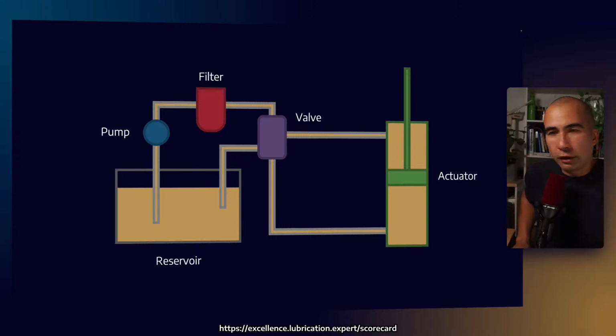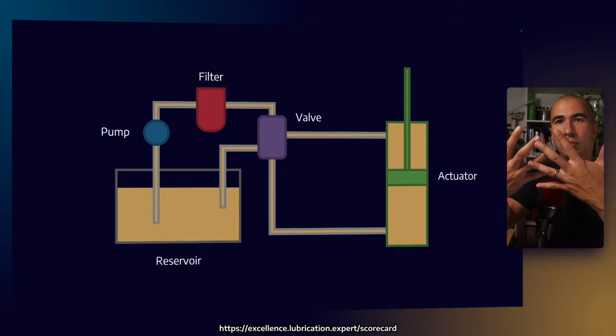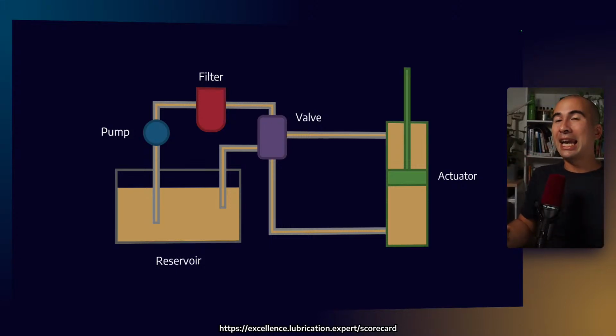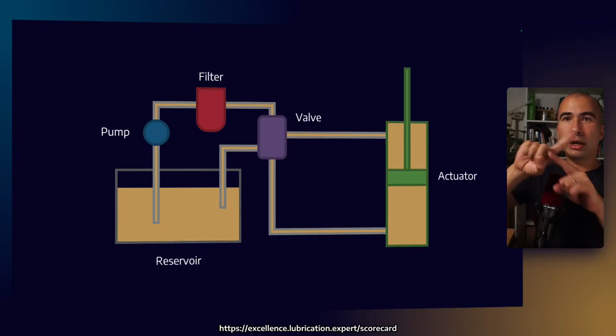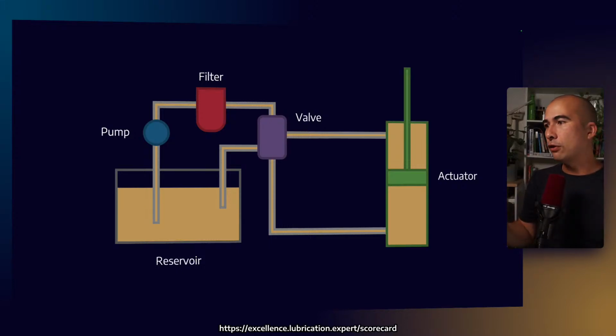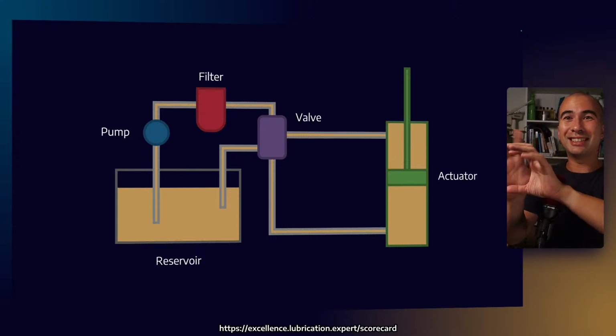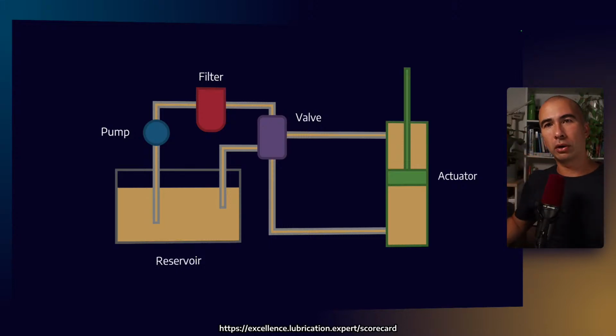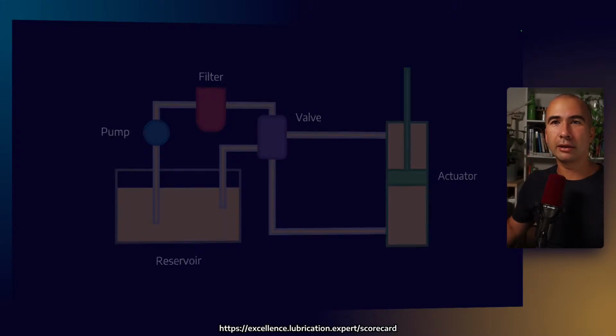If you think of, for example, a gear pump, you've got the gear mesh, which is potentially going to wear. In a vane pump, it is the sliding action of the vane on the outer casing. If you think of another kind of pump, the piston pump, it's the action of the pistons against the swash plate where most of the wear occurs. So that's why hydraulic oils tend to contain a fair bit of anti-wear additives.